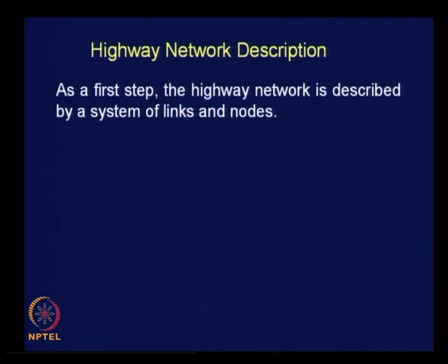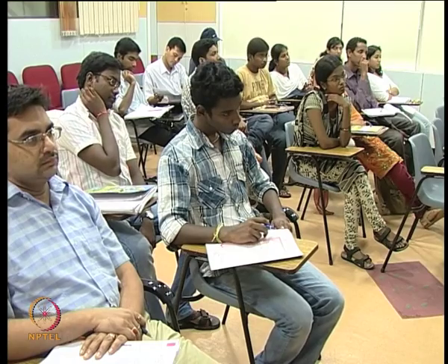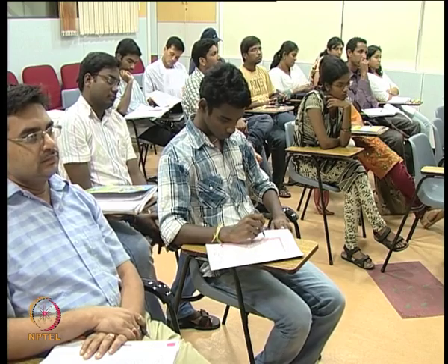So having discussed in detail about the three aspects, what are the three aspects? First one was related to conversion of person trips into vehicular trips. Second one was related to temporal variation of travel demand, and third one was related to direction of movement. Okay. So, all these three aspects are to be given required attention while you start assigning traffic on various routes.